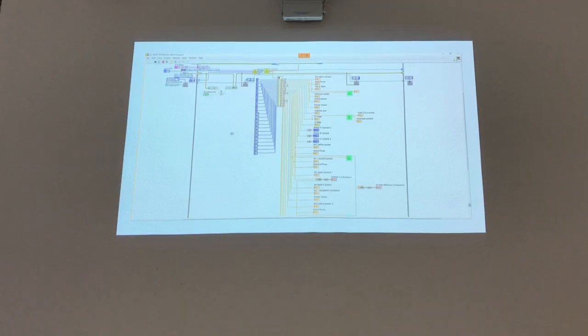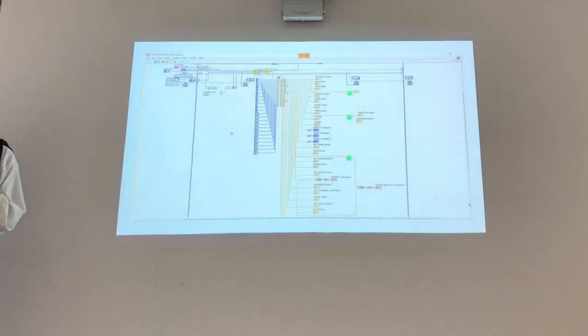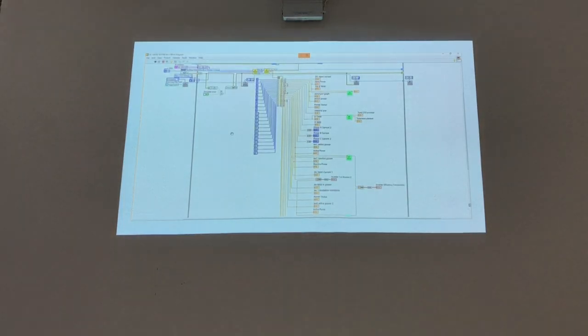So overall, what is your take about efficiency here? I think efficiency is very important to calculate, especially in this kind of system where you have input and output. Using this efficiency, you can really see what parts are not working and what parts are working. For example, when I calculate the inverter efficiency and the overall system efficiency, if the overall system is lower or higher than the inverter efficiency, then that means there might be something wrong with the inverters.